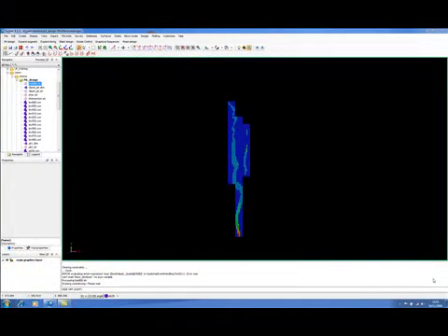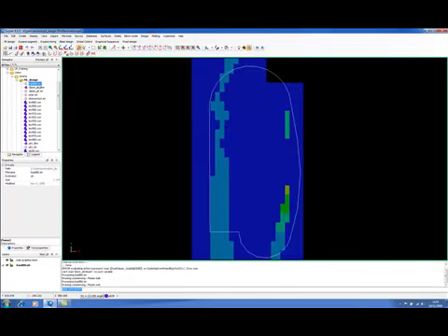This short movie will show the use of pit design tools in Surpac. The design of the pit starts with defining the starting string. Starting string is a closed polygon located either on the top of the pit or on the bottom of the pit.